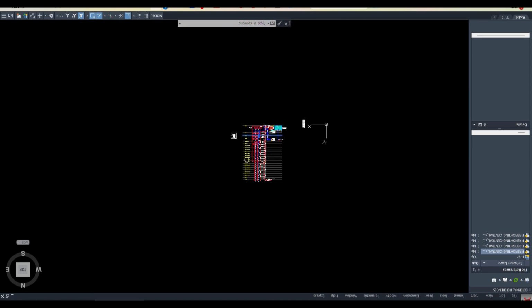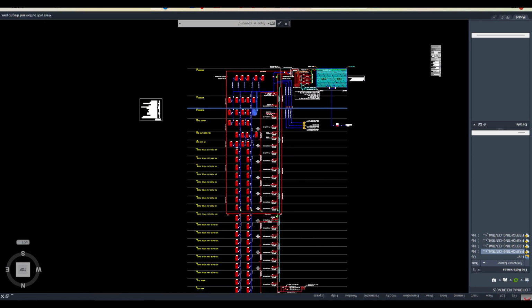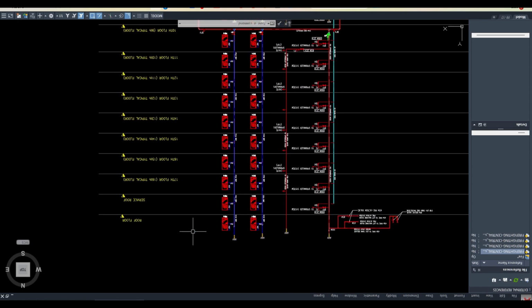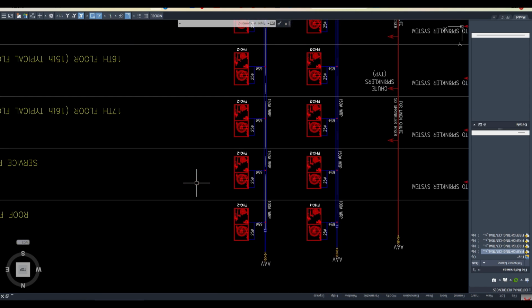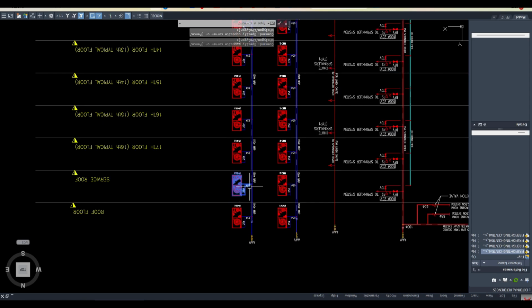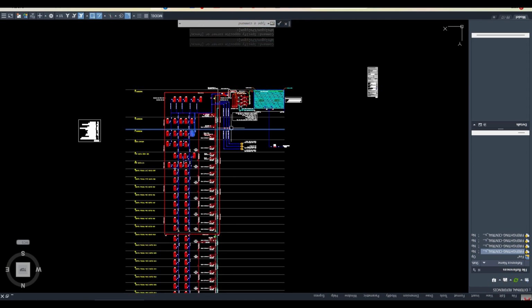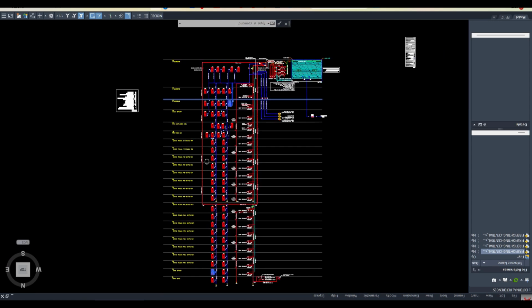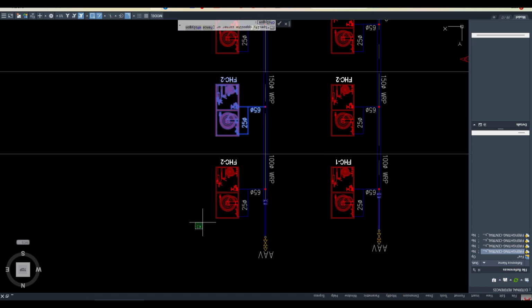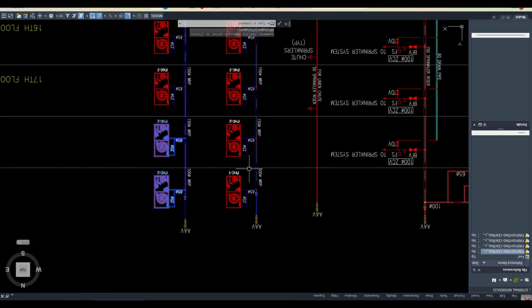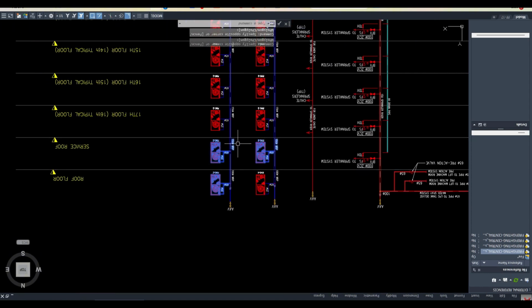The pump sizing is a design part. Still, I will tell you that when the fire designers design this piping system, they consider one fire in one case. The design criteria is that one fire will happen on one floor, and that way they will design it. So the system is not meant to operate all the fire hose cabinets of the building at the same time. Suppose he is selecting the pump, he has to consider one fire on one floor.